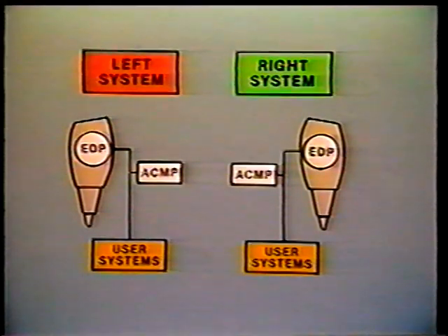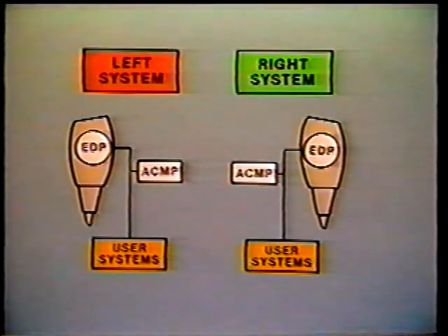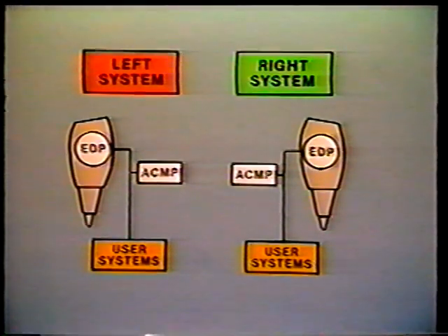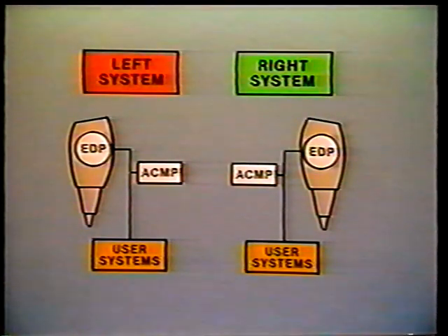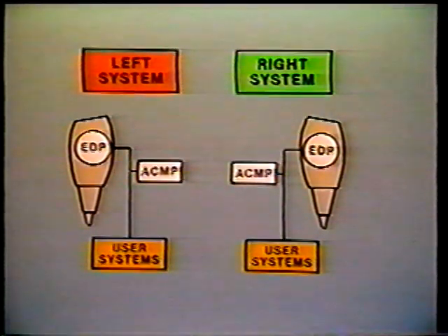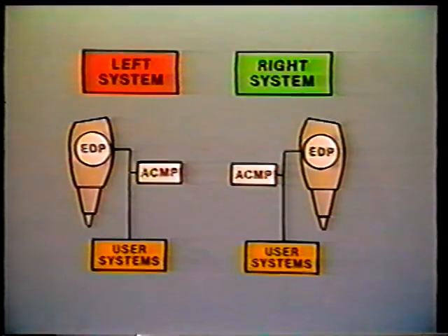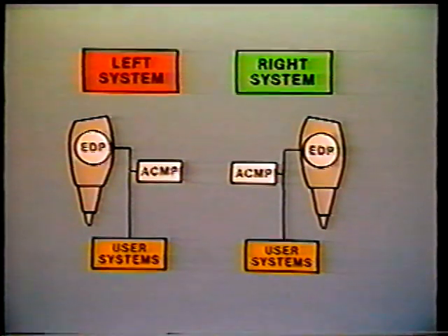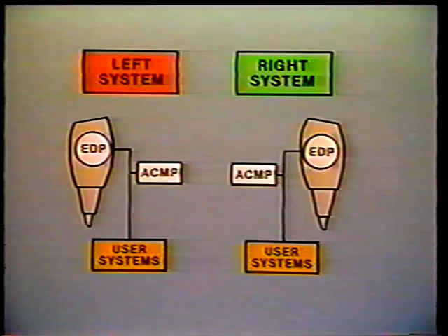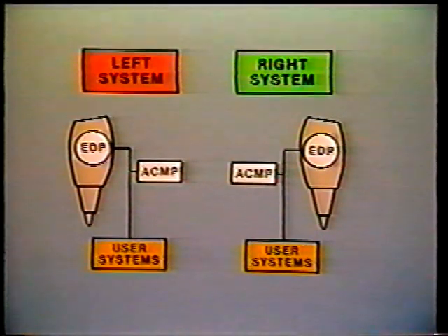Let's quickly review the pumps on the three hydraulic systems. The left and right systems are powered by an engine-driven pump, or EDP, and an alternating current motor pump, or ACMP. Both pumps are normally operated full-time. The EDPs are mounted on the right side of each engine on the accessory gearbox. The ACMPs are located in corresponding left and right wheel well areas.